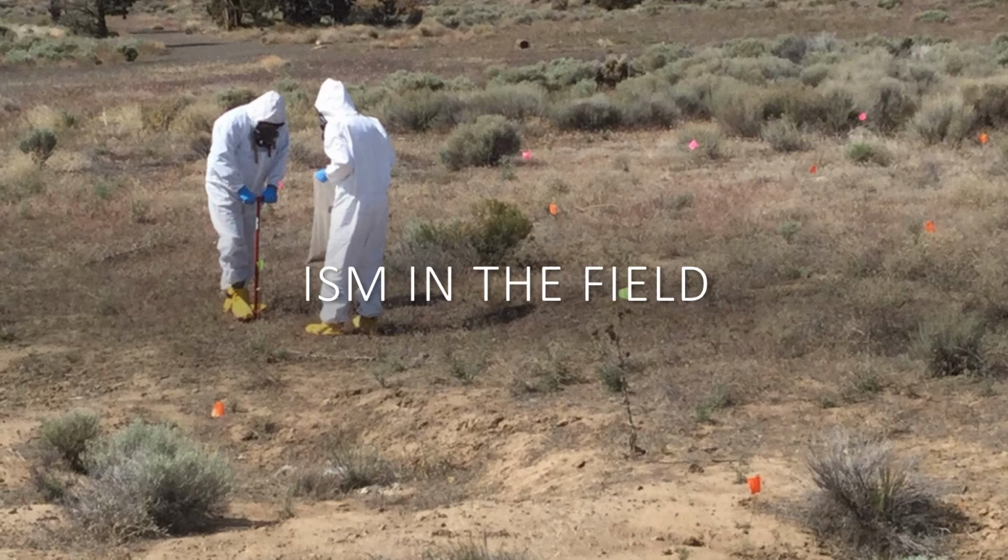Another advantage of incremental sampling techniques is that the samplers become very familiar with the soil conditions throughout the site. In the photograph above, a coworker and I are collecting 5 100 increment replicate samples within a quarter-acre decision unit in Oregon. At the end of the sampling, we had collected 500 total increments in our decision unit.